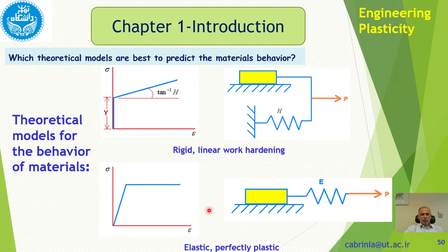For instance, if you bend the plate, it assumes a curvature by plastic deformation, but after plastic deformation we have some spring back which is elastic. So we must have a model which includes some elastic behavior, otherwise we could not predict the spring back. We will come to solve such problems later on.